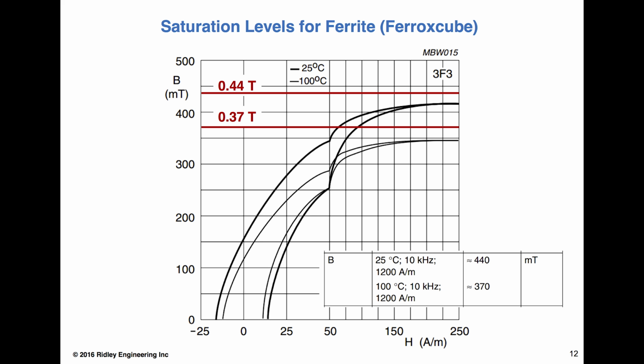And as an experienced engineer, you test and you measure temperatures, and then you add what you think is a reasonable boundary on top of that. But it certainly would be nice to see that pinned down a little more. But from what I gather, the manufacturing of ferrites and ceramic materials in general is not an easy process. And trying to get an upper boundary on what the core loss really is going to be is difficult for them. If we can just get them to give us much more extensive data and all the data, I think that's probably the most we can ask for from them.